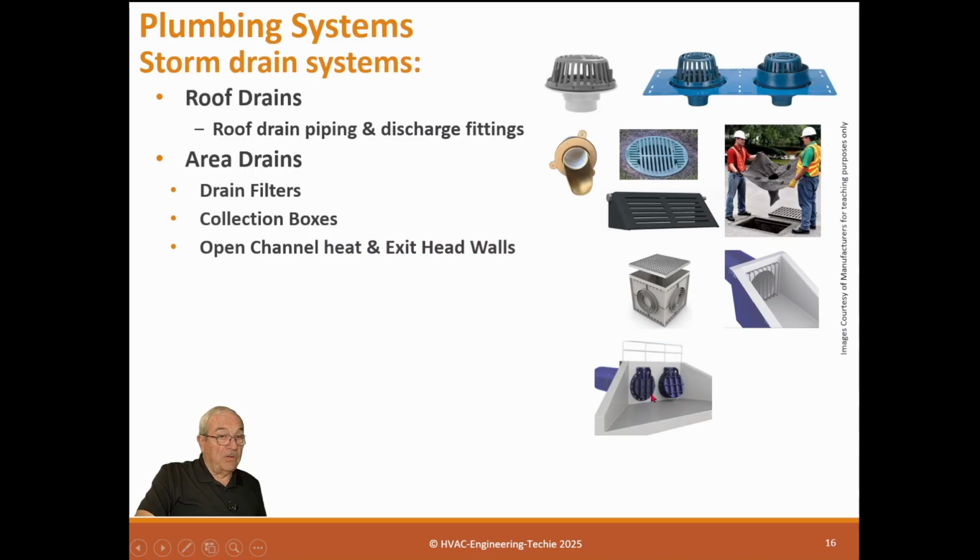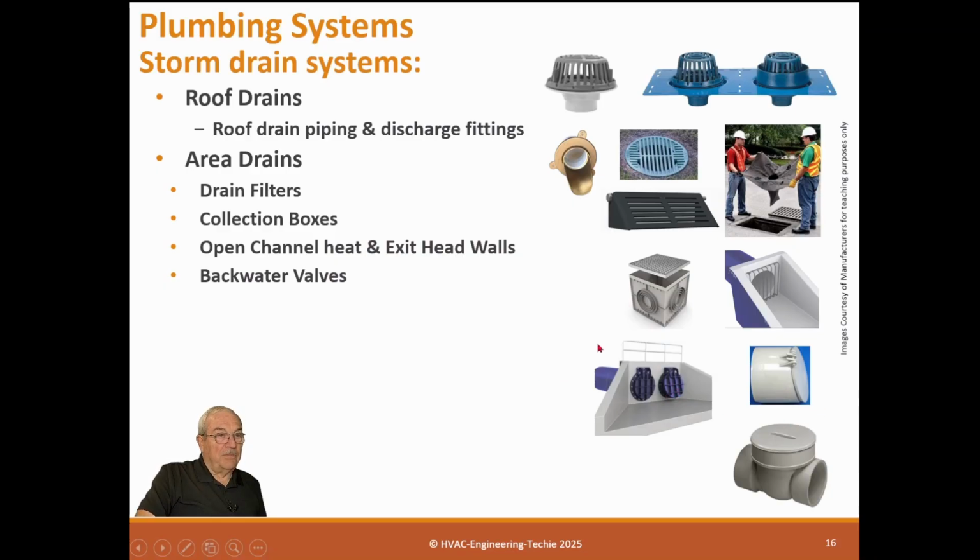This one has to be a backwater valve, so if this was in a waterway or something, you put a backwater valve on it to keep it from flooding. If the river is flooding, you don't want the water coming back up in your building. And of course, there's separate backwater valves again to prevent that from happening.